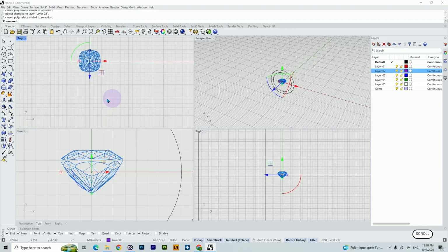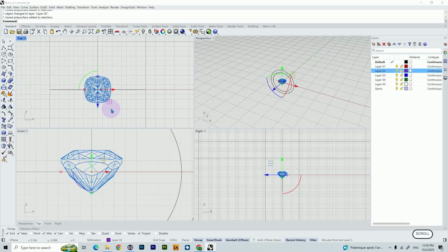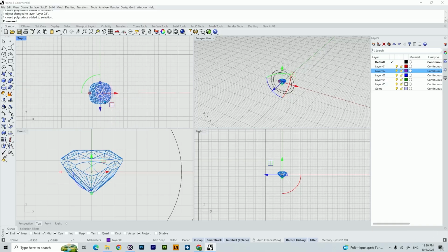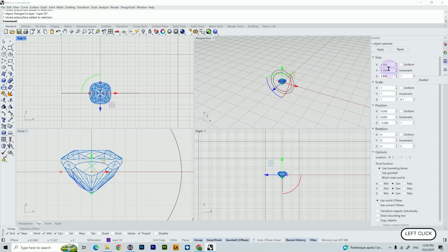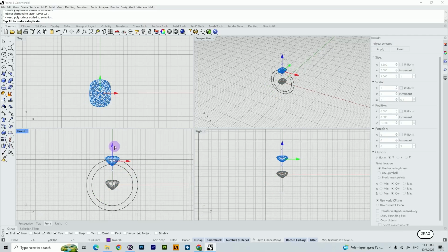And for this tutorial, let's play around a little bit and make this cushion gemstone into something rectangular. I believe it is called a rectangular cushion gemstone or whatever. So I'm going to navigate to the box tab right here, and for the Y parameter I'm going to say 7 millimeter. Press enter. Now we have set the size. Let's put this into place somewhere around here.